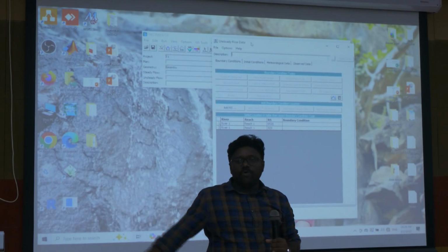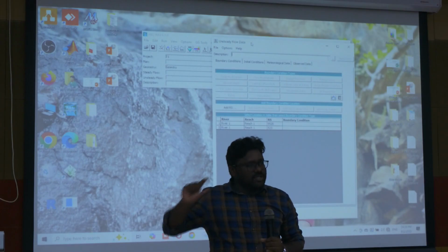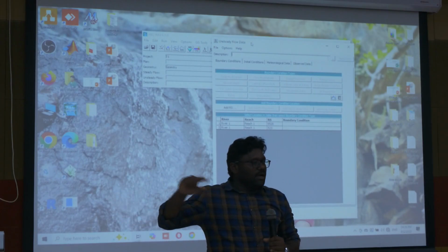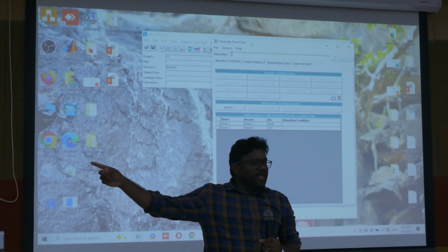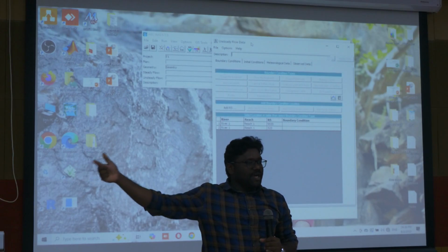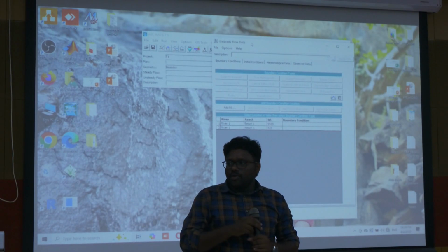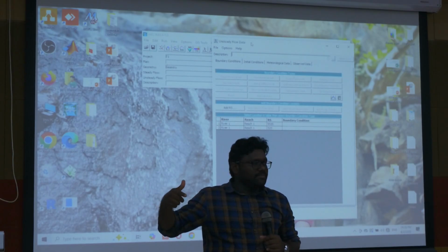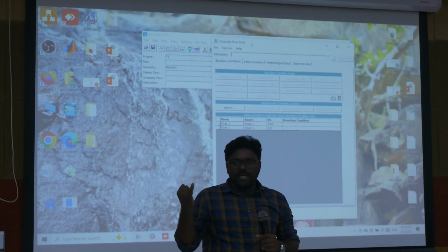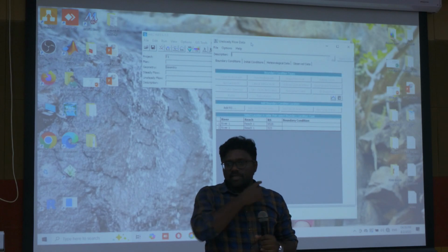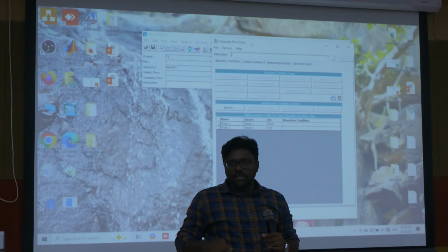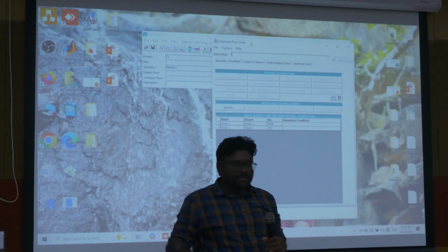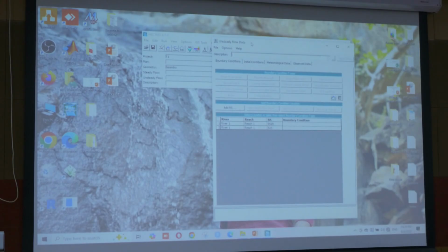As it is a uniform flow, the bed slope will be equal to the friction slope. So Q is area into velocity, and in that velocity we are giving the friction slope. Velocity is a function of depth. We know the Q, so it will calculate the depth. Understood? Our upstream boundary condition is our upstream flow, that is the simulated flow at the outlet of the Netravati basin. Then the downstream condition is the friction slope. So first we will give the upstream boundary condition.